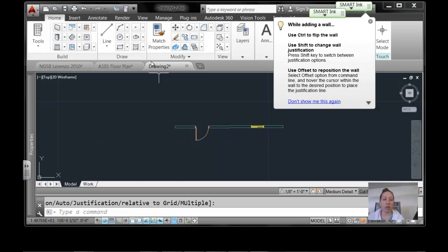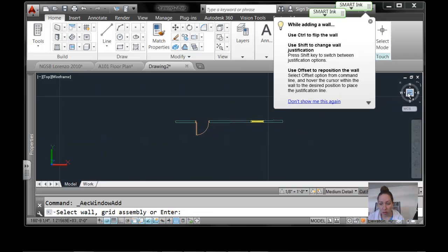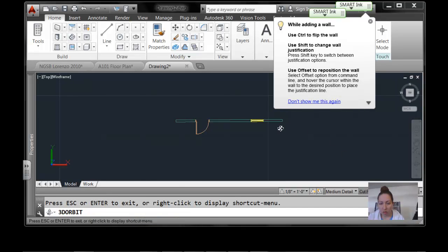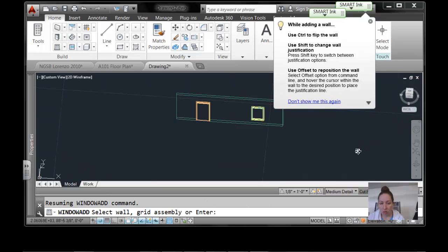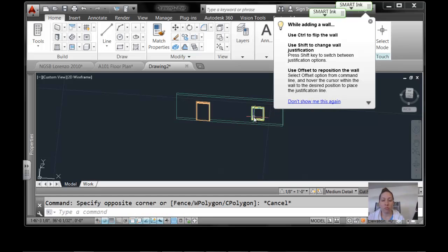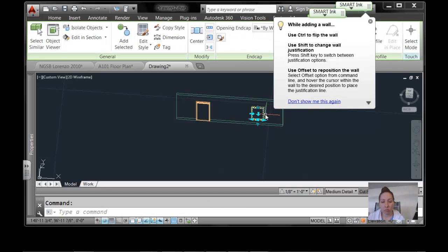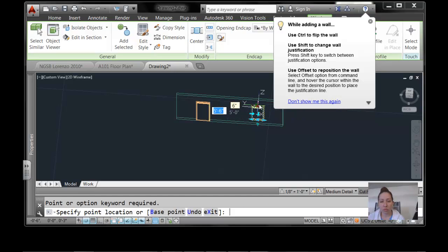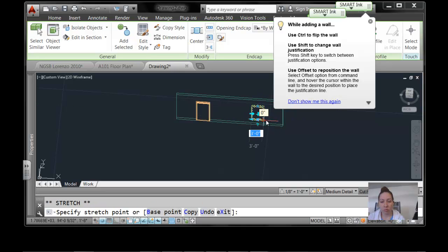You can also adjust the size of the window. And that you're looking at the wall from the front view. You can click at the window and adjust the size. Okay, the edge, on one of the right or the left. Excellent, there. So yeah, AutoCAD is very picky where you click. So now you gotta go right click. Oh, there you go. So you can augment it, just literally dragging the arrow up or down. You can change the dimension.